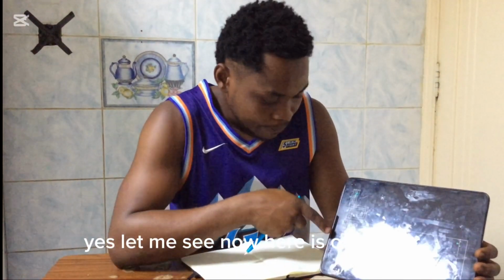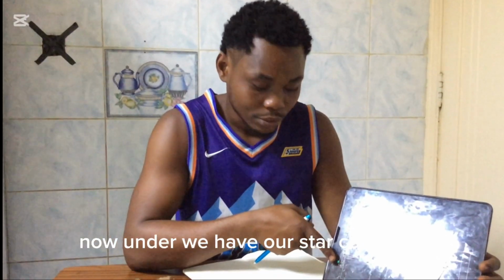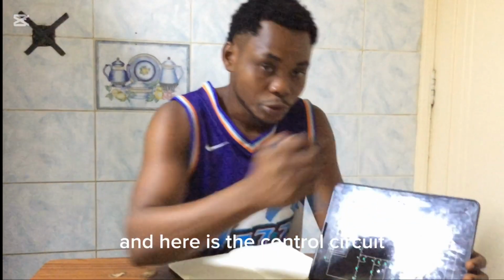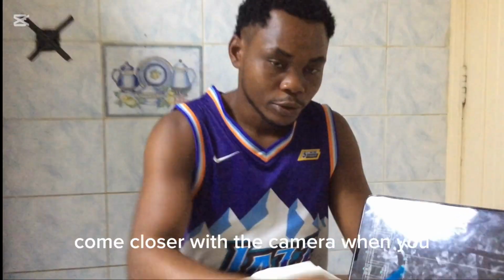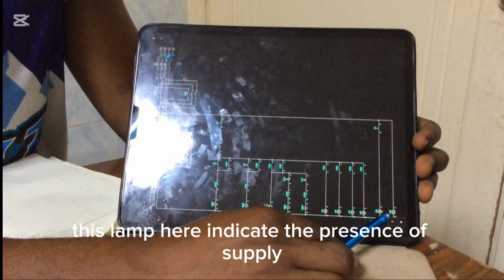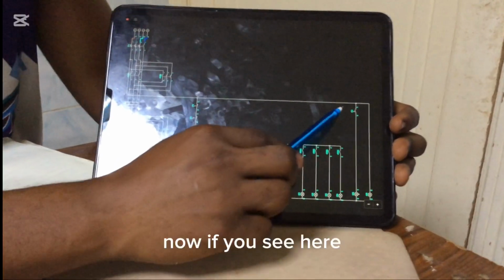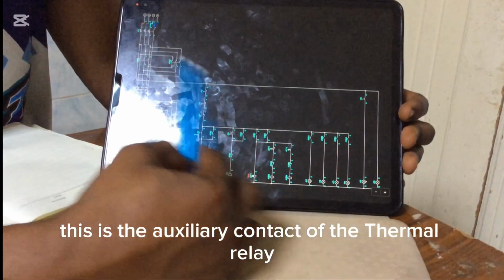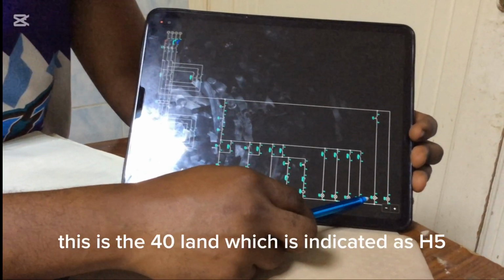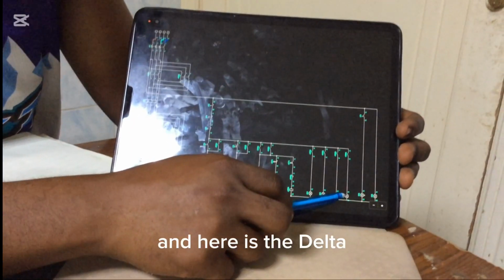Now here's our motor. Under the motor we have our star contactor. Here we have our delta contactor, and here is the control circuit. Come closer with the camera. When you take a good look here, this lamp indicates the presence of supply, denoted as H6. Now here is the auxiliary contact of the thermal relay, which indicates the faulty lamp. This is the faulty lamp, denoted as H5, and here is the delta.